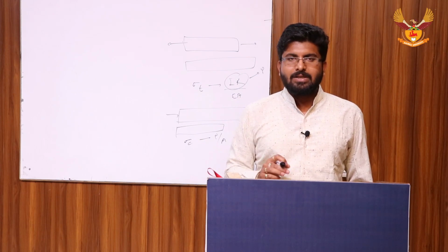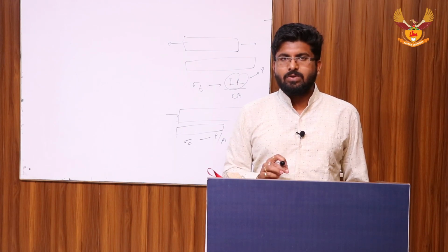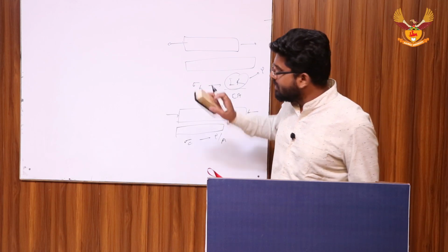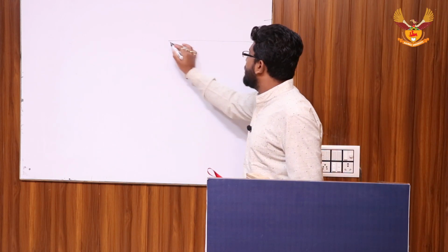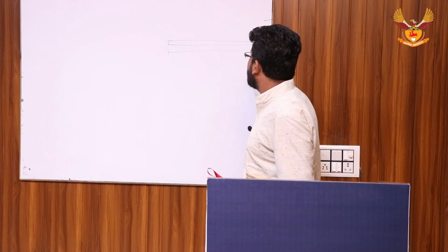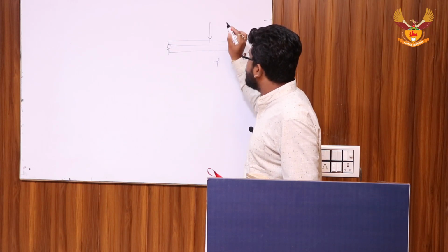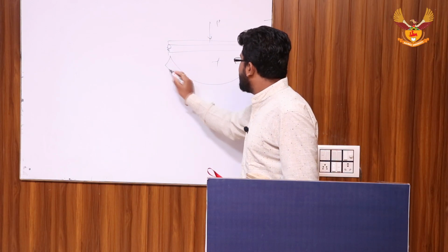And another one is indirect stress, in which force is applied in an indirect loading condition. Then it is further classified into two parts: bending stress and torsional stress. First we define bending stress. Suppose this is a bar having a length L and supported by a knife edge support. We apply a load P. Due to this force, the body will deflect.